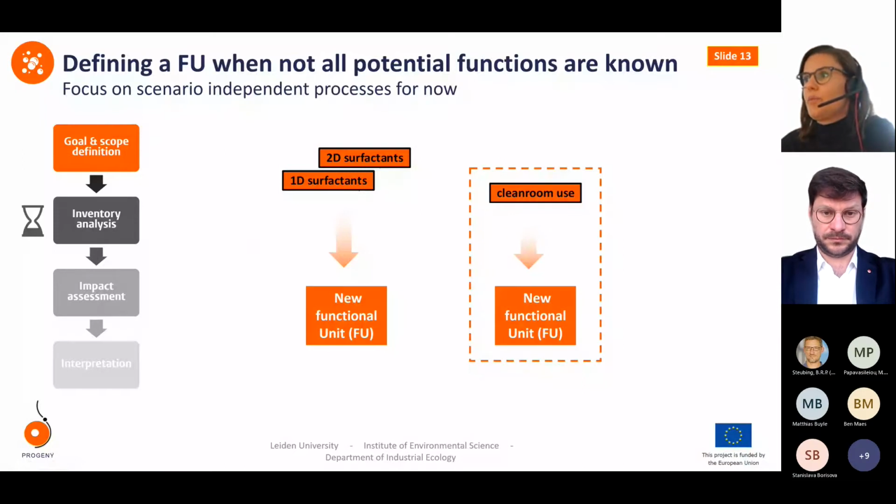One of these unit processes which we probably will need is the usage of a clean room, a defined space where the device can be assembled, free from dust and any kind of particles. But we do not know which ISO standard of clean room we need. Is it ISO standard 1, which is super strict and very, very clean, or is it maybe ISO standard 6 or something in between?